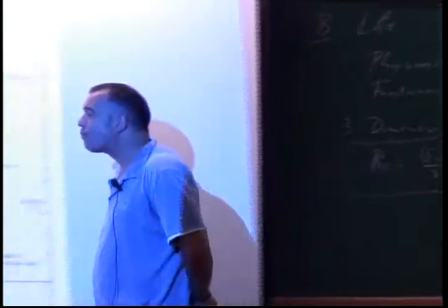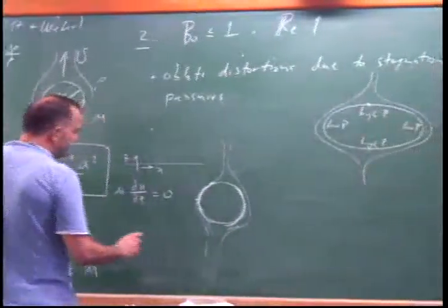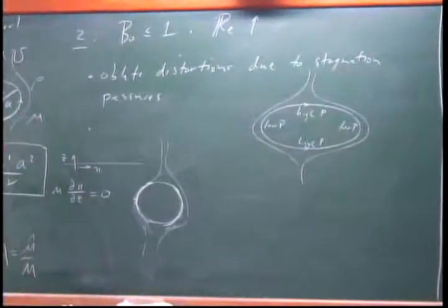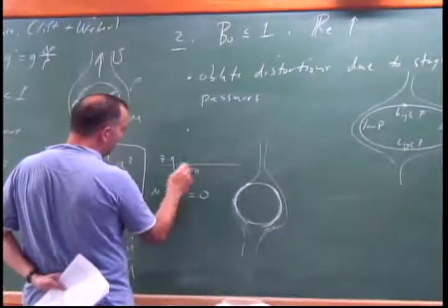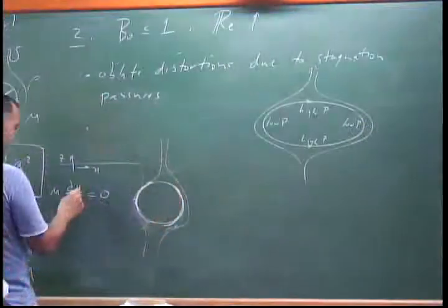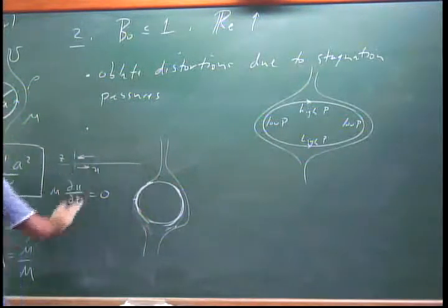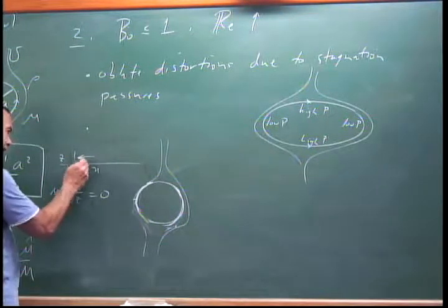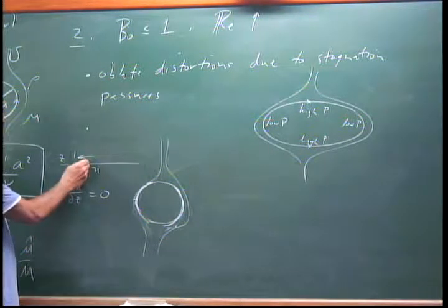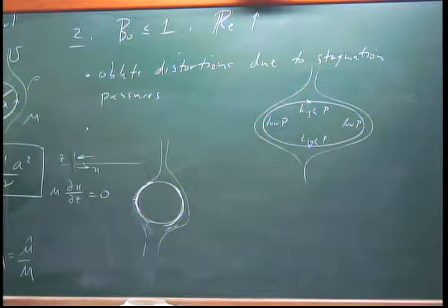But it's a little bit like modeling the bubble as a vortex sheet. So which one could do. Right, that's right. There is basically a vortex sheet, but you do have an interfacial boundary condition. So you want to have this, right? This is the vortex sheet problem. Velocity has to be continuous at the interface, and you have to have a balance of viscous stresses. Yeah, it's not continuous, it has a jump. Right, this is what the model does.